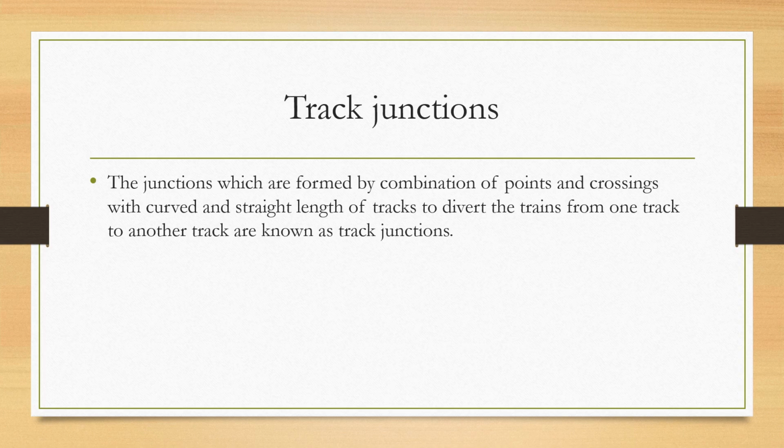Crossover. The arrangement made in the form of two sets of turnouts, with or without a straight length between them, which connect two parallel tracks for transferring a train from one track to the other, is known as crossover.